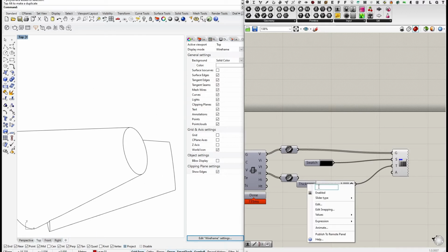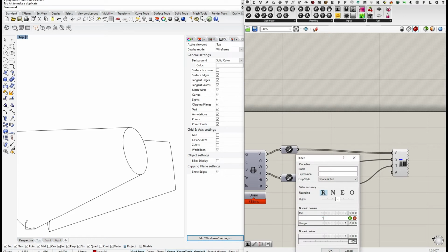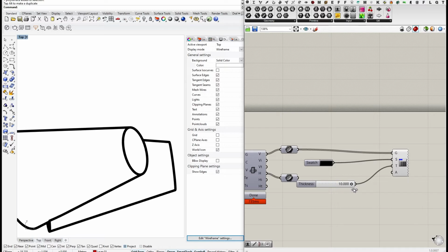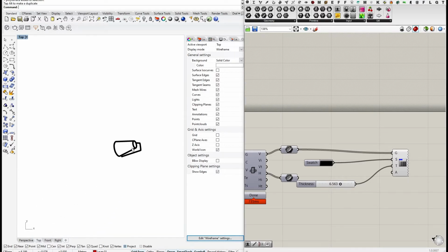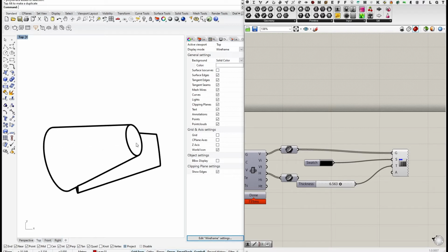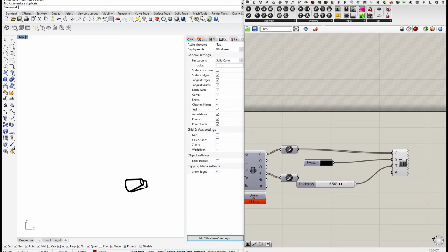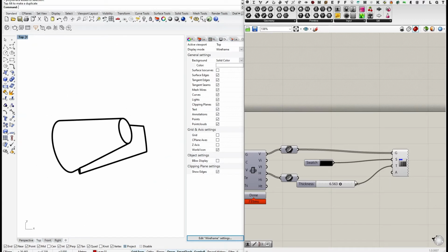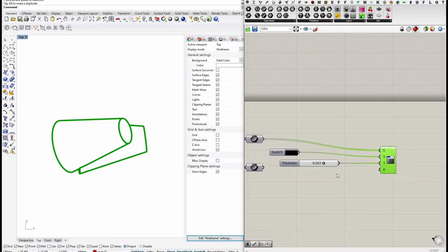If we increase the values of the slider to 10, you will see I can increase the line weights by pixel, but it's always an absolute pixel. So if I zoom out, the line thickness stays the same, but of course the impression of the drawing becomes very thick lines for a drawing this small and very thin lines for a drawing this far zoomed in. You can switch this line thickness also to render them according to absolute values, which is the last option that you have here.